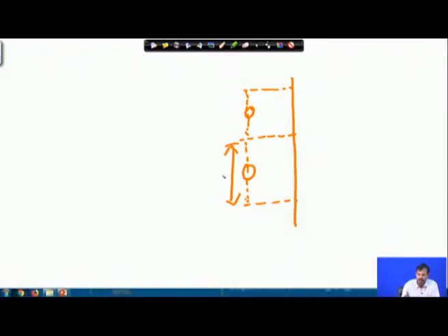If there are 2 holes in one row, placed side by side, the zone of influence of blasting for the first hole is up to this and for the second hole is up to this. So, this distance is what we term the spacing of the holes.